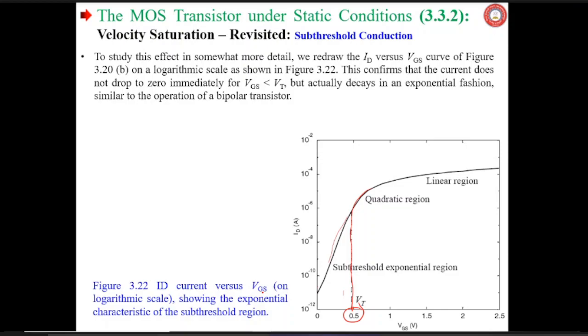And we have defined also the subthreshold slope. Earlier we have written eta. This symbol was eta, and this equation also we have seen with VGS minus VT, but here only VGS is written. Remember that device modeling is done with different resources, and for a single thing you will get various equations. So it is not unexpected that VT is not written here, but mostly the VGS minus VT equation will be always available in the literature.